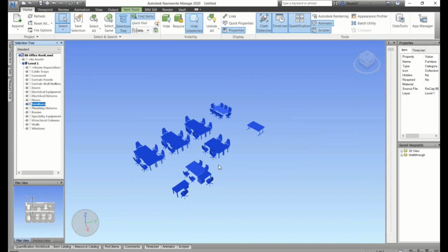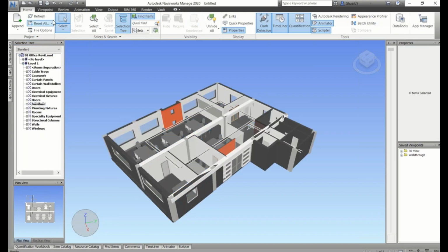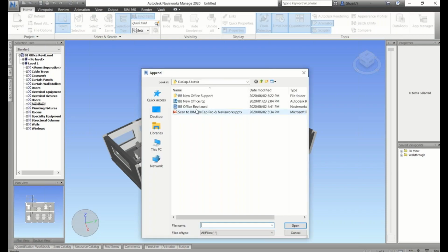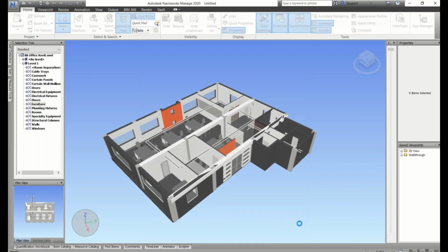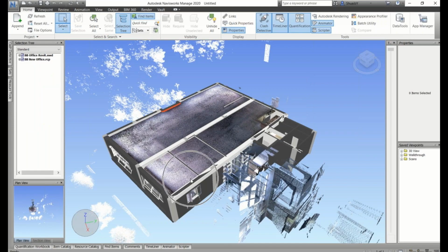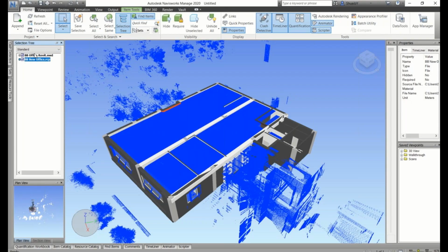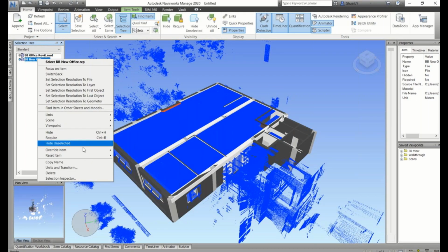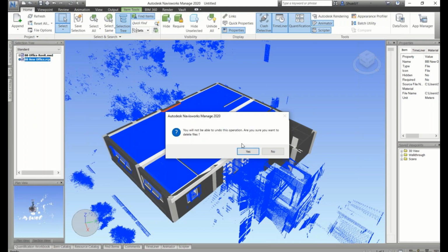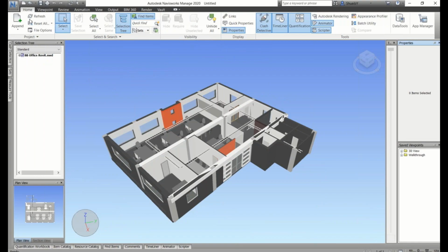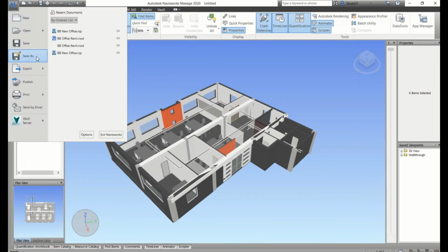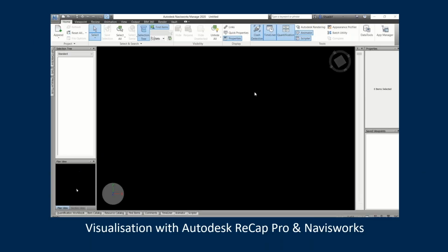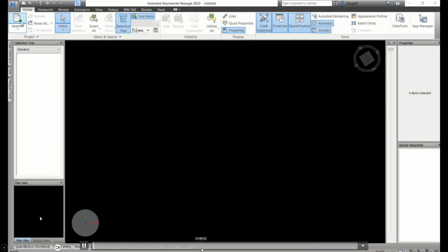And of course, with Navisworks, with the selection tree on the left-hand side, you could really mold this or visualize the things that are important. And as you can see, my point cloud sits exactly where the model is. So if you have this problem, line it up here and then proceed to the steps you're going to see in a bit. Okay. Right, so this is Navisworks, the Revit model in Navisworks. I can save it as an NWD and we're good to go. Actually, let me show you this very quickly. So once we've got this saved as an NWD file, let me just skip a bit.